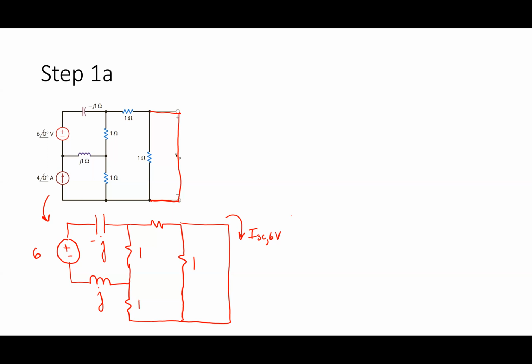Okay. And the reason why all of it goes through the 0 ohms is because the voltage across the resistor is 0. When the voltage across the resistor is 0, the current through it is 0. All right, always think in terms of KVL and Ohm's law, right? All right, so we're going to simplify that down.